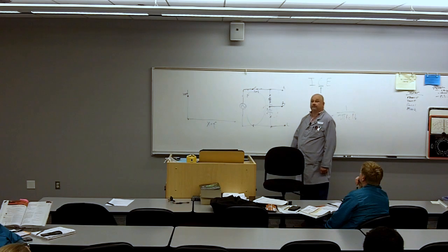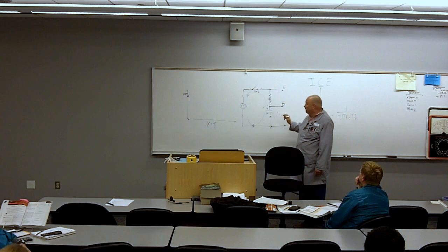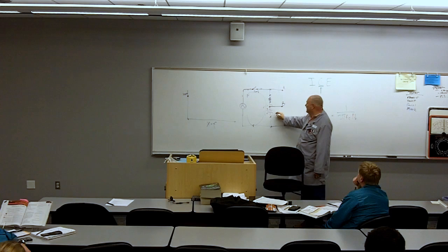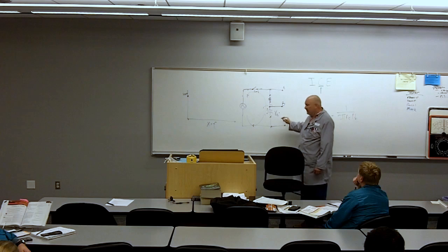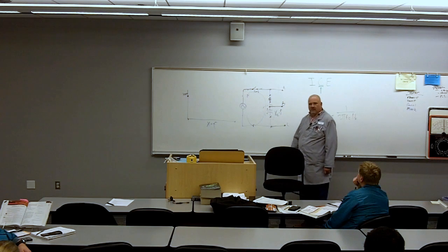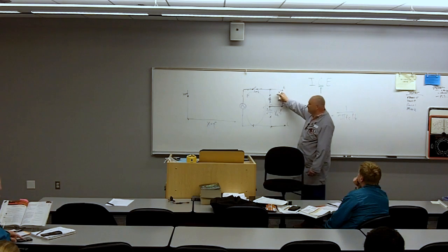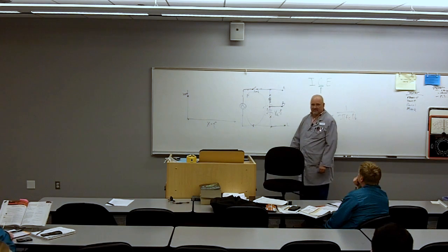What's that? Daniel? It's not going to have any effect on it because the resistor is purely resistive. So frequency is not going to have an effect on this. But when I put a low frequency into this, the value of, what property do we measure here that's so important to us? Reactance. How do we abbreviate that? X sub C is going to be extremely high. And what's this measuring? Ohms. So this is going to be a huge value here at a low frequency. This is just going to be whatever value it is.